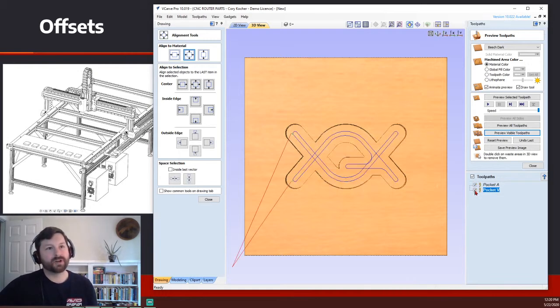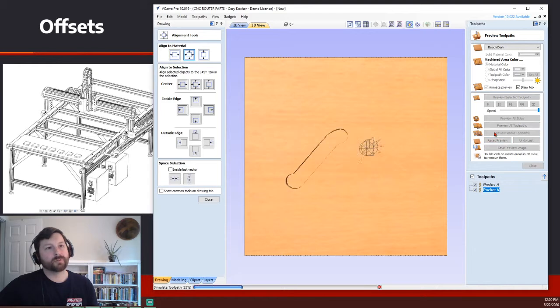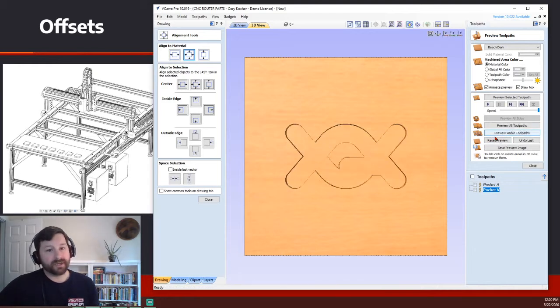And running this program on the same workpiece would obviously not be ideal. But the important thing is that both of these are using the same offset point from the corner. And the corner isn't the fixture, the corner is the workpiece. And this is where we're going to be able to take advantage of some serious production capabilities with your machine.